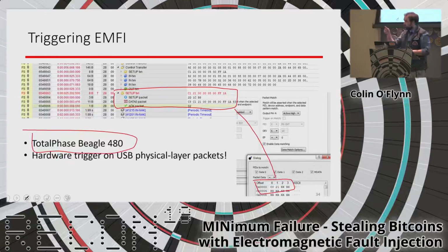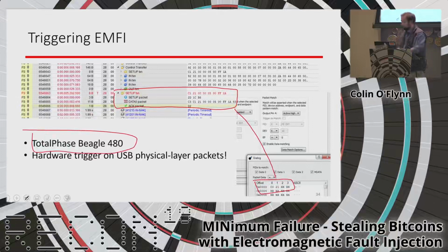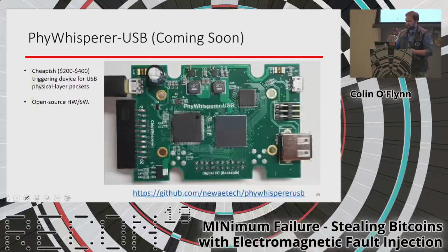It goes across the wire, the device is going to process that at some point later in time, so I know if I insert a glitch, if I get lucky, I'm going to hit that exact moment. It's not super reliable for timing. There's some jitter due to a queue that processes the message on the Trezor side, so I can't get a 100% success rate. But if it works once over an hour, then you get a dump of everything. So you only really need it to work once.